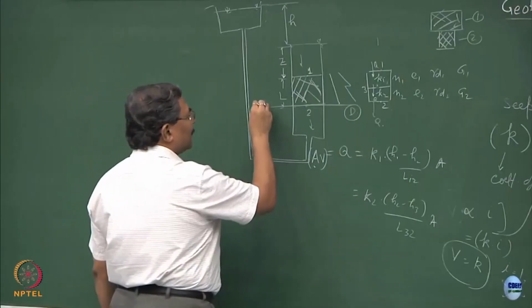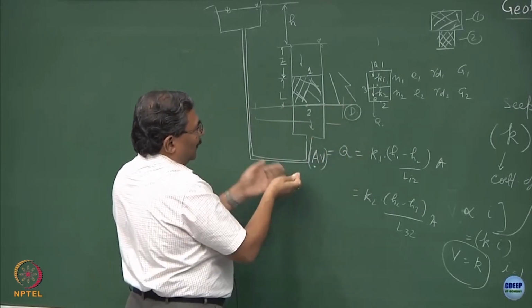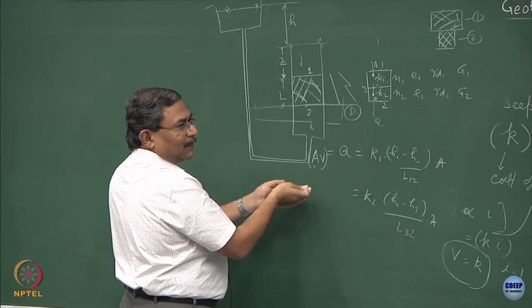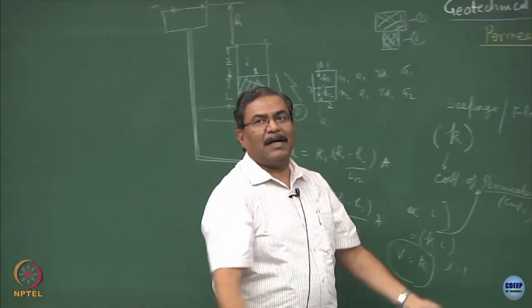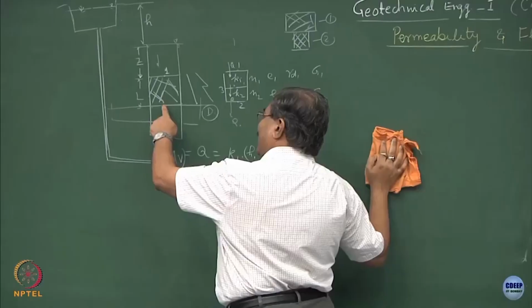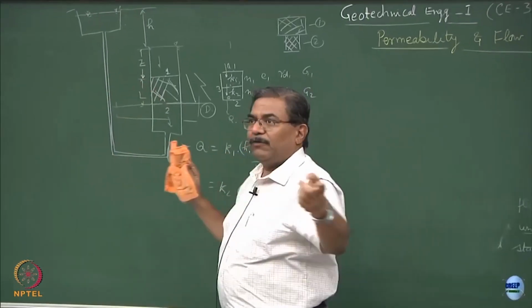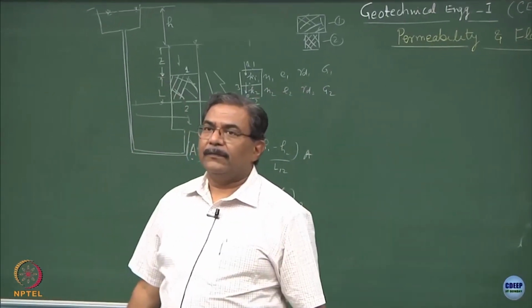It is the same thing. In the previous case, what did I do? How does it matter whether you are keeping it in a tube connected to this or whether this whole thing is inside a water bath? It does not matter. If you are putting vacuum over here, it does not matter, keep the datum as it is. Pressure head at this point will become minus of your value of vacuum which you are applying, that is it.